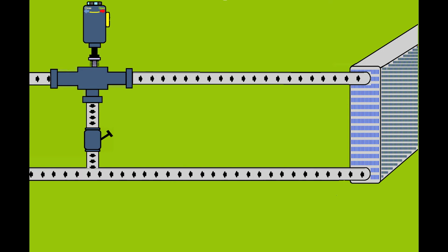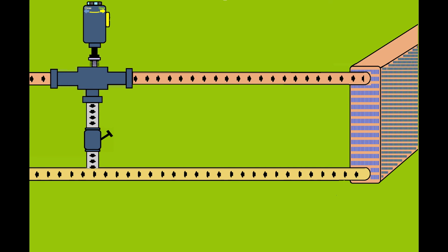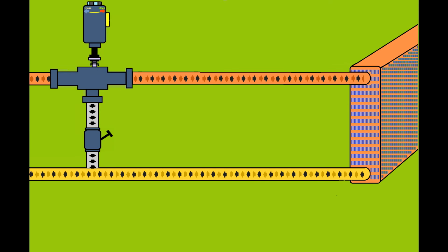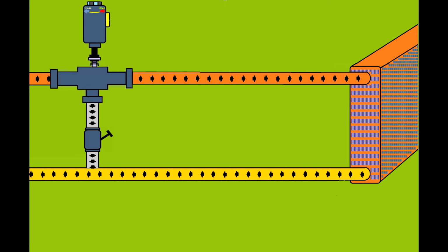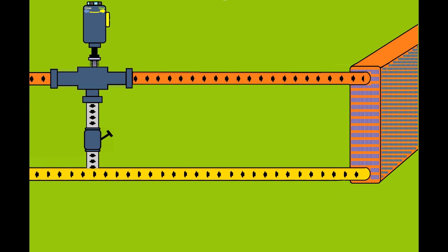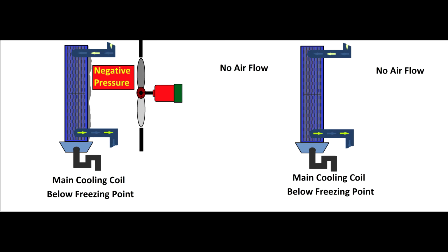If the boiler or the chiller doesn't work, you wouldn't expect to have cooling or heating even if the valve is 100% open. You have to heat the heating agent before it hits the heat exchanger. So sometimes it doesn't matter if you open 100%, the actuator and the valve will allow the heating agent to flow. If the boiler is not heating the heating agent, then you won't heat the heat exchanger.